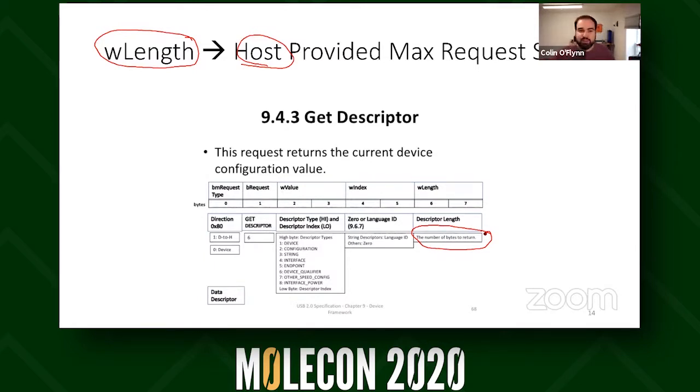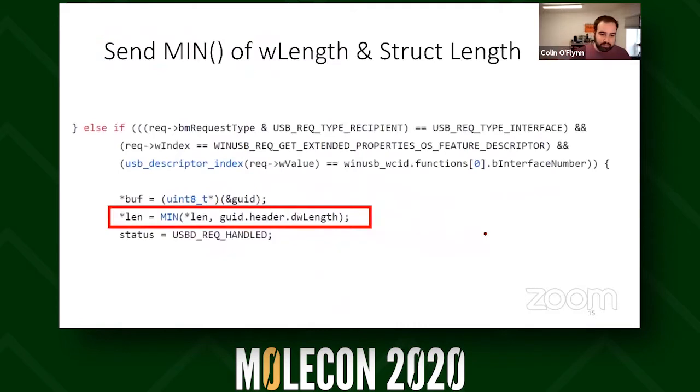So this idea was in the USB spec, so everybody has to implement it, right, to be a legitimate USB device. And what this means is that somewhere in basically every USB stack is this call. And this call is a bunch of stuff saying, for one specific descriptor, right? So it's checking the type, it's checking this index property to figure out, is this the right descriptor that I want to request? So this is the device code, by the way. Sorry. So this is the code running on your device.